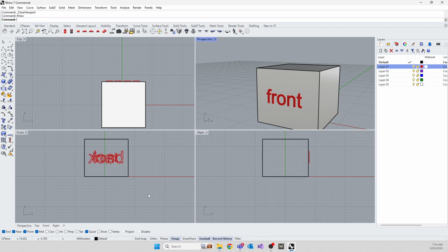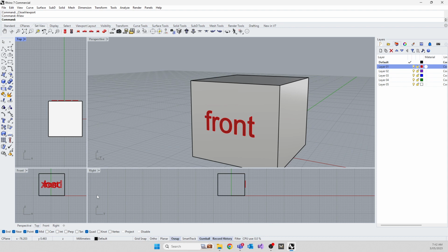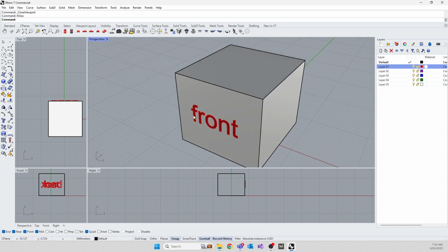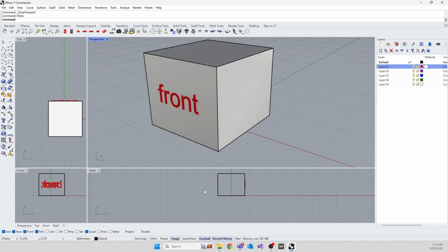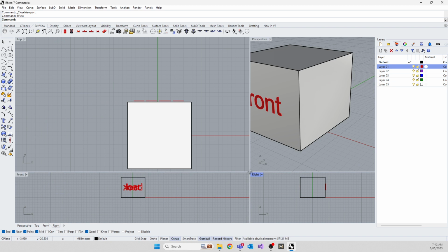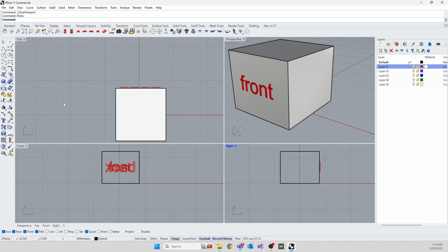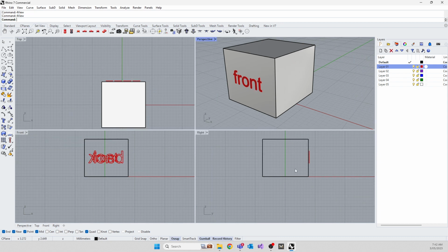For view. If you want to share your space around, you can go in the middle of the viewports. And when you're happy with that viewport, you can even save the layout. So a lot of people like to work like this if they're working on curves. If they're working on geometry, they may not want to. They want to work maybe just with the standard view. So you can move your viewports out. The command again when everything goes wrong is for view.